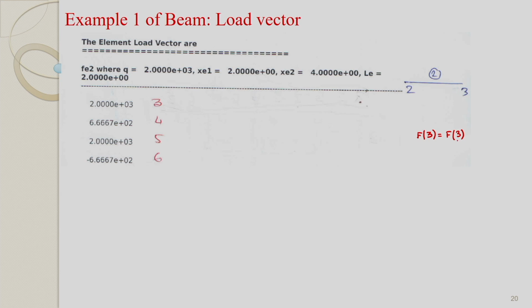So, at the third entry of the global load vector, this point load will be directly added, and the point moment will be associated with the rotation degree of freedom of the corresponding node.